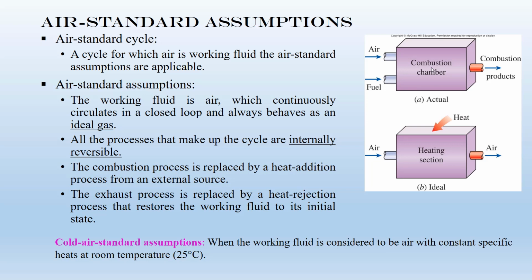In this assumption, first we assume that air is the main working fluid of the combustion chamber. So we cancel the fuel. We just assume that we have the air. What is the application of this assumption? The application is that to calculate Q here, you just need to use the thermophysical properties of air.